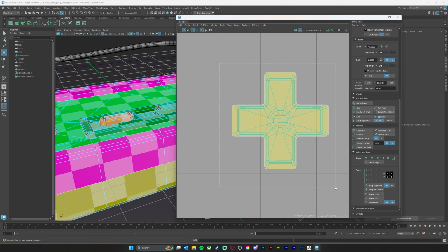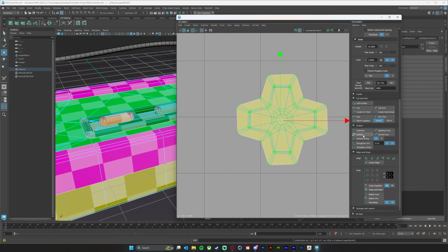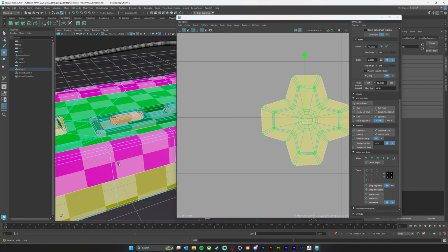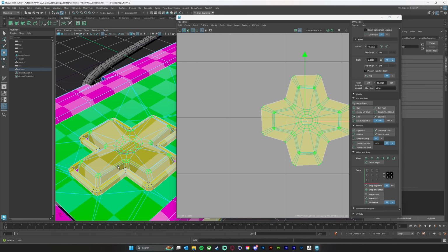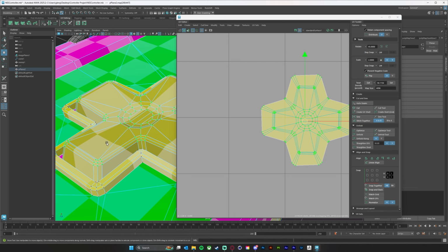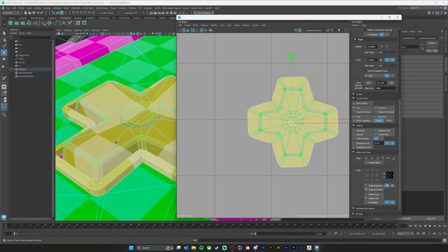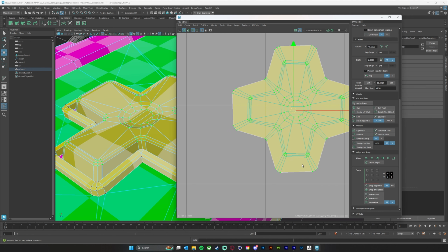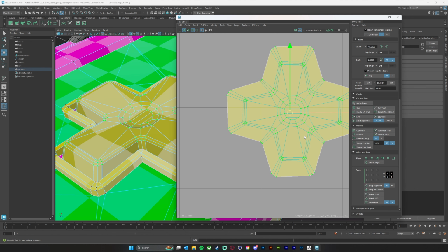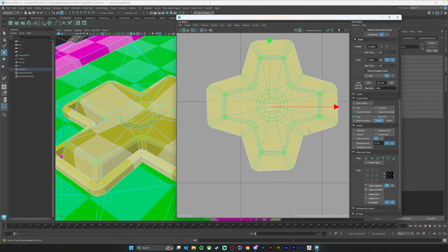We can certainly try just selecting it and doing an unfold, but it doesn't quite look right, right? We're going to start seeing here in our 3D view these squares getting a little stretched and a little wobbly. So we want to try to do this a bit differently. I think the way I want to do this is actually cut the top surface of that D-pad off, and UV it on its own, and then we'll UV the outer surface on its own.